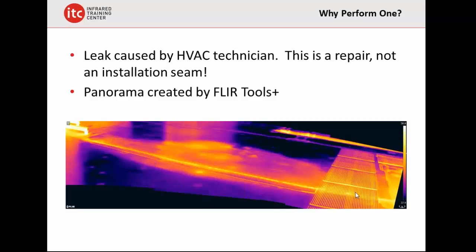This is the repair. We even put the walking pad on. I mean, we added an HVAC unit over here later on, but this is actually a repair sitting right there from a leak. And this is also an indication, you might wonder why it's still there. This is about 4 years after it was caused, and the moisture is still underneath here because the company that repaired it did not take the water out of the insulation.